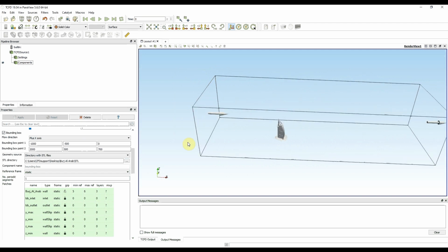This is good computational area for tutorials or initial cases where you want to set some baseline and make just case running. But if you want to get proper results, I recommend you to use even larger bounding boxes with maybe huge computational area to be sure that boundary conditions does not influence your results.